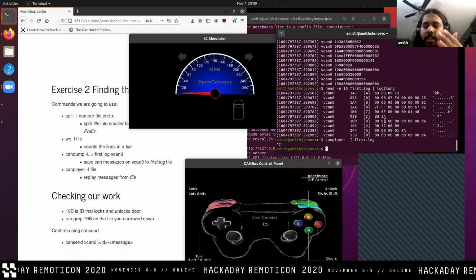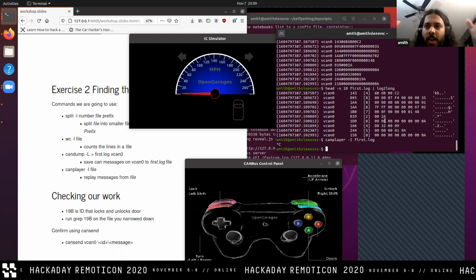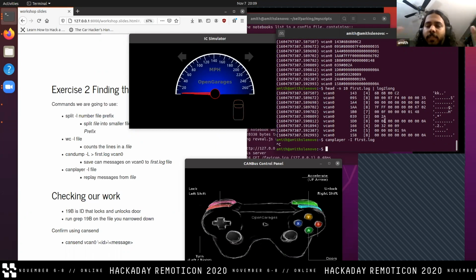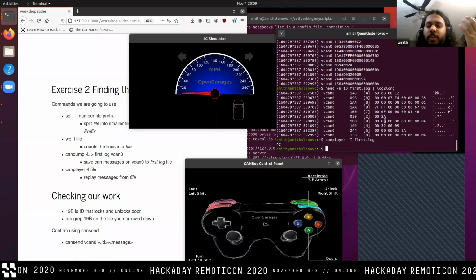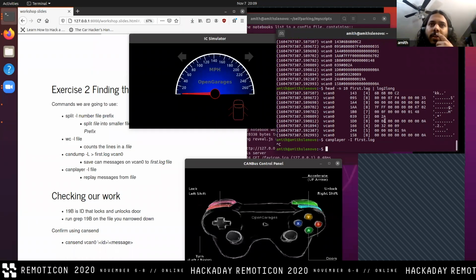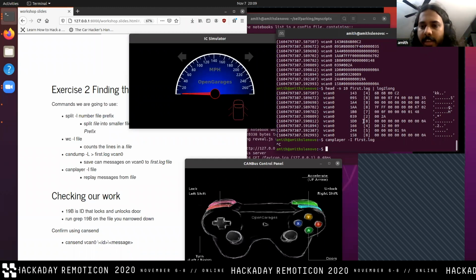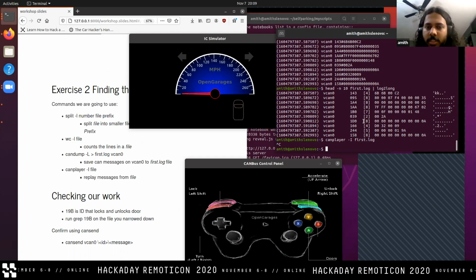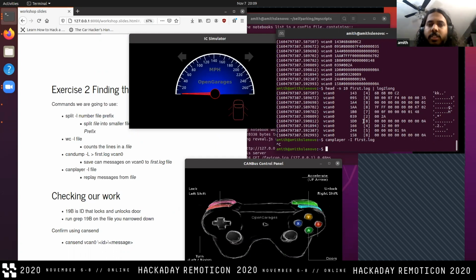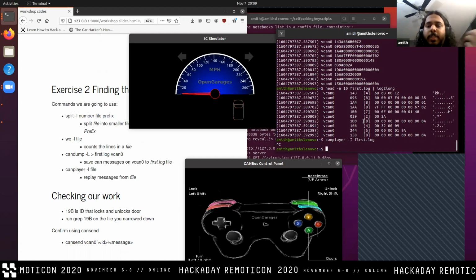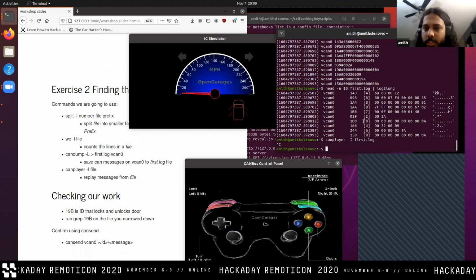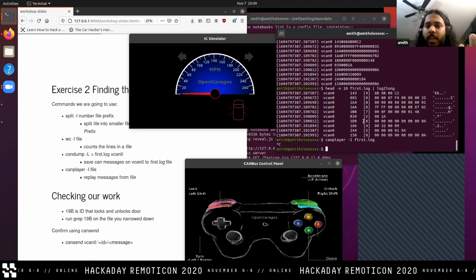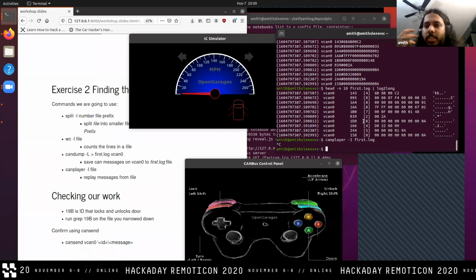that CAN file, or the CAN dump log, into 2 files and replay each of them to see which section of the log unlocks the doors. So if we split the original file into 2 files, each with half the CAN messages, then we replay the first half and see if that unlocks our doors again. If it does, great. That means the CAN message we're looking for is in that part. Otherwise, we know it's in the other half.